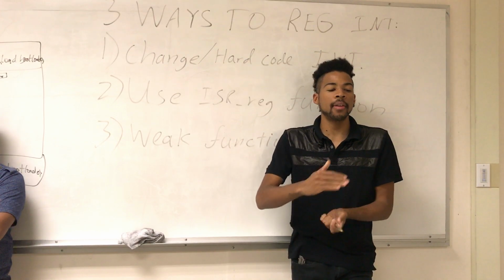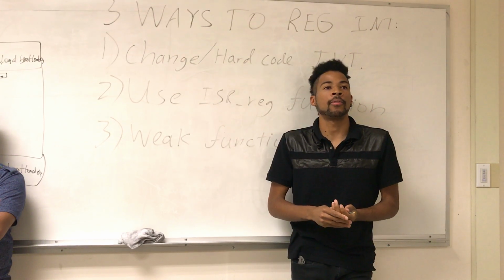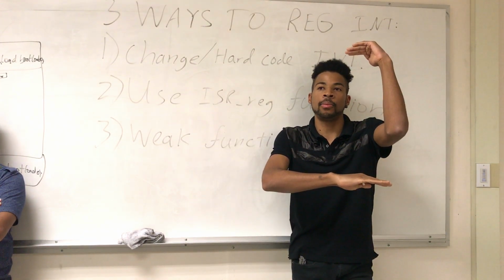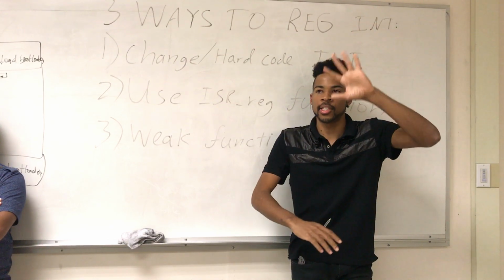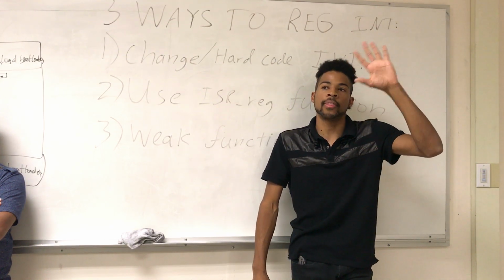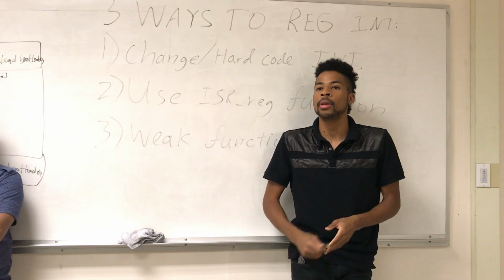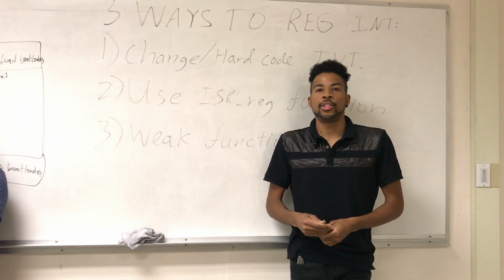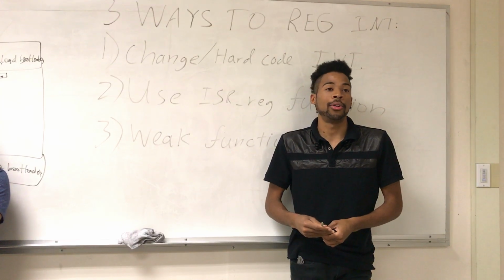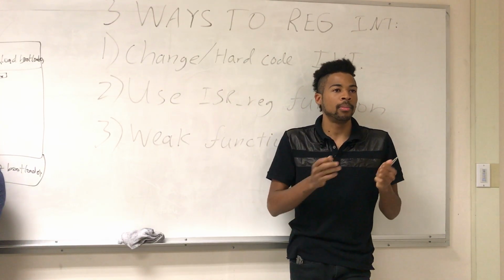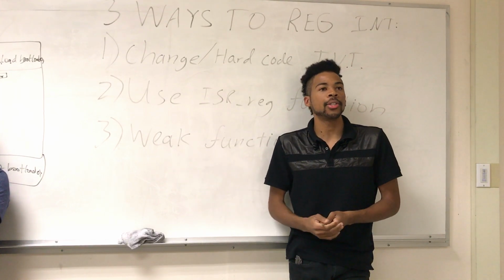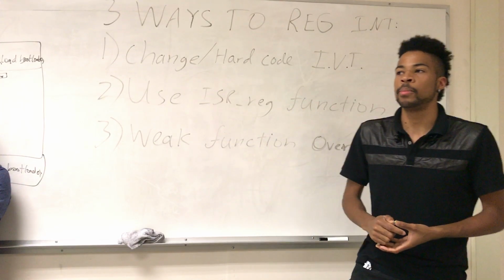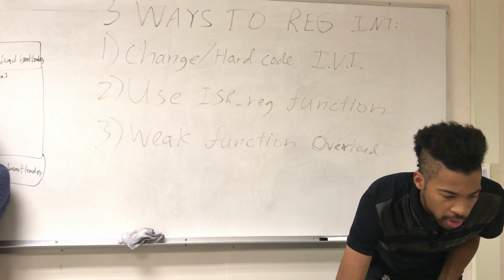Okay? I'll make sure I have this listed out, because that's what I want you to do for my class. A way to get around this is, like I said before, that entire list of things that I put in the last discussion for SPI, the extra things I went over for my SPI lab. I want you to look at that and use those same things for this lab. You don't really need to use unions, but you're going to be using structs. You're probably going to be using function pointers. You're probably going to need to remember how to use pointers appropriately, and not just simple one-way pointers, maybe even double pointers. Okay. So you should be able to attach an interrupt to any particular pin, and on top of that, you need to run some service routine.